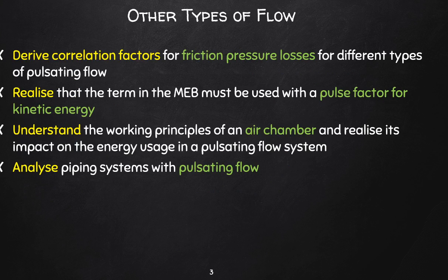and also ways that we can deal with changes in or fluctuations in these pulsating flows in our design and operation of piping systems. This includes the use of correlation factors or safety factors to account for a periodic fluctuation, and also how to dampen such fluctuations, because sometimes you can't change the fluid mover, you'll just have to try and dissipate fluctuations.